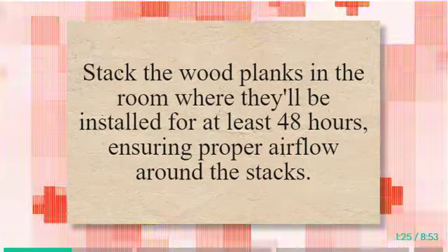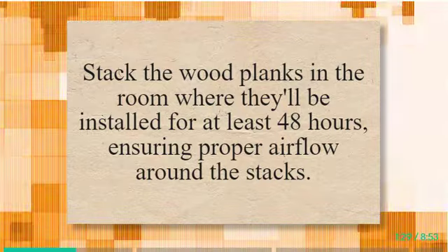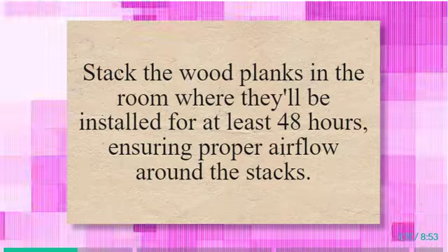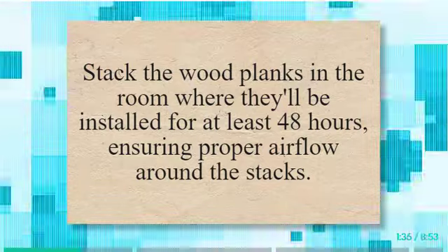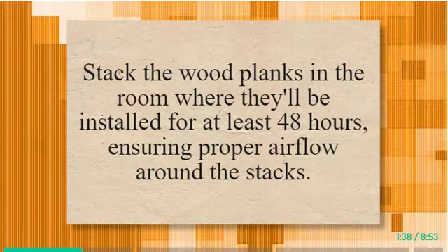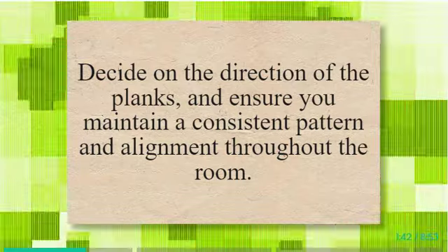Step 4. Acclimate the wood flooring. Wood is sensitive to changes in temperature and humidity, so it's essential to acclimate your wood flooring to the room's conditions before installation. Stack the wood planks in the room where they'll be installed for at least 48 hours, ensuring proper airflow around the stacks.